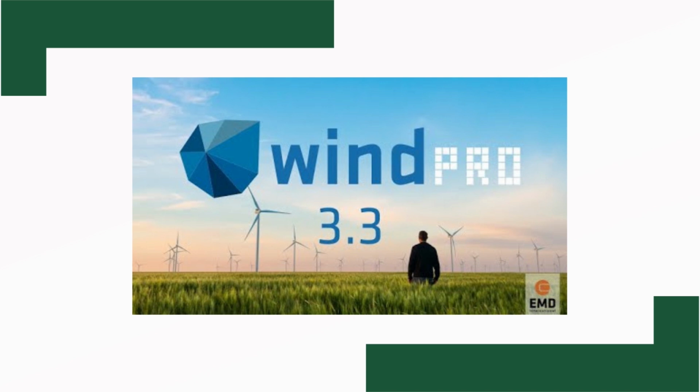After installation, we need to launch WindPro and create a new project for our wind energy assessment. Once the project has been created, we need to import or create a digital elevation model, similar to WASP. This data helps in assessing the wind flow over the landscape.